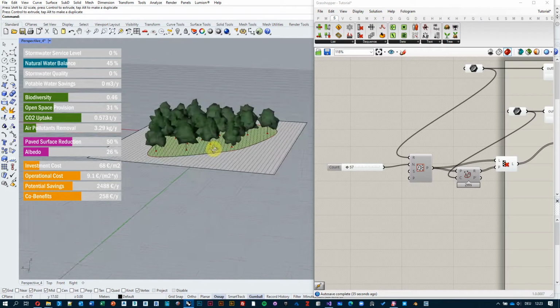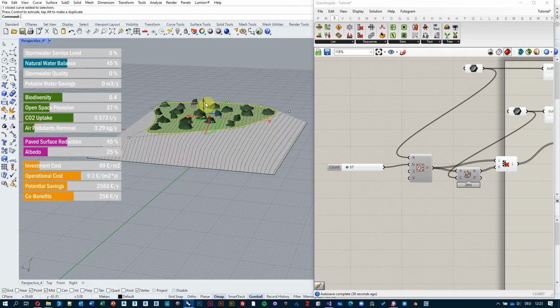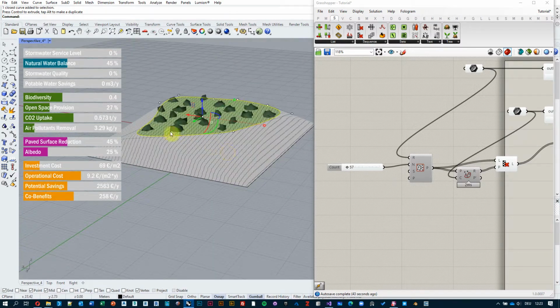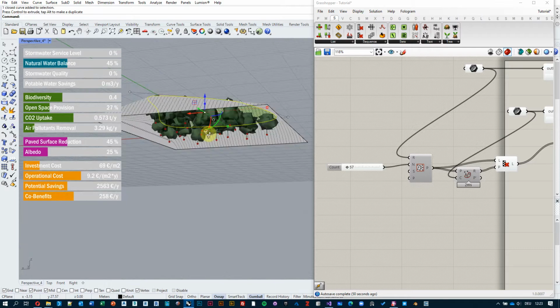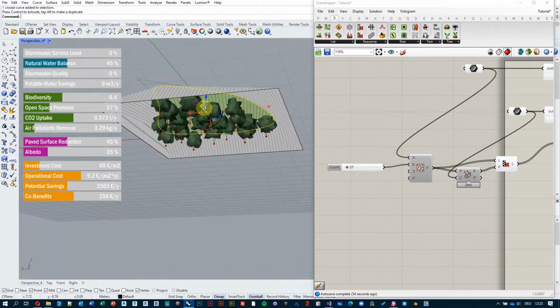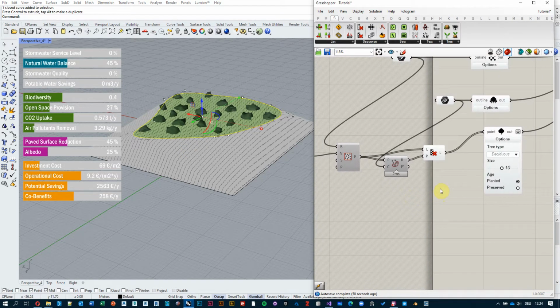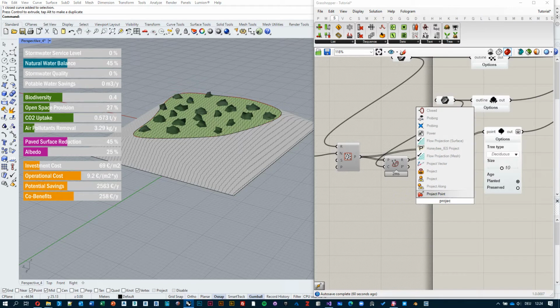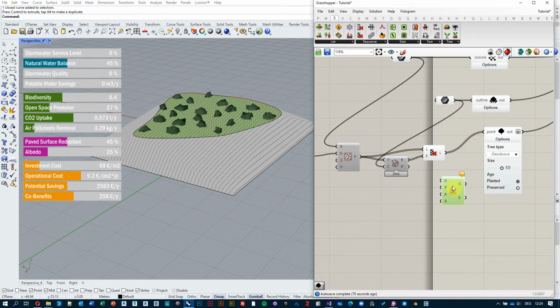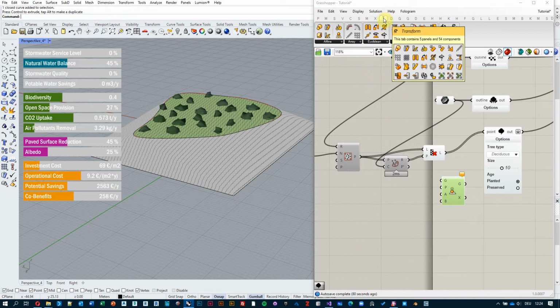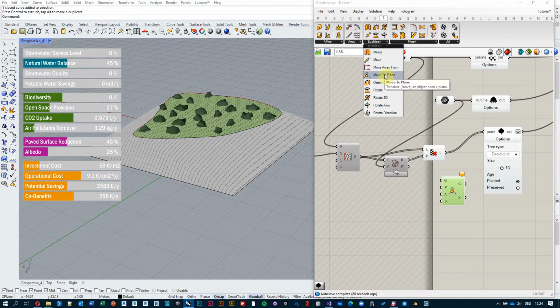And then another step that we could take is if, for example, this is a three-dimensional drawing, and we wanted to raise this green area element above the surrounding terrain. We would see that our points fall within the boundary, but they still remain at 0. So again, we could use Grasshopper's tools. Sorry, it's move to plane, not project to plane. Move to plane is a component that's also built into Grasshopper, and it's under transform. We can see it here, move to plane.